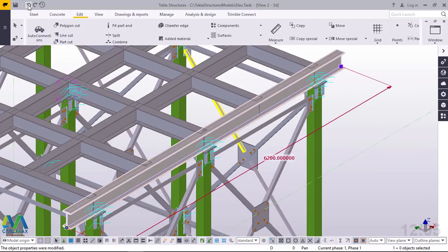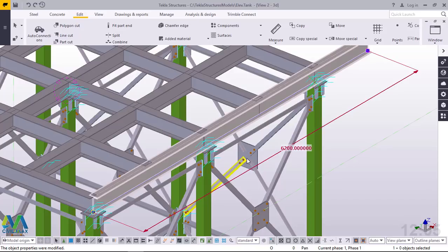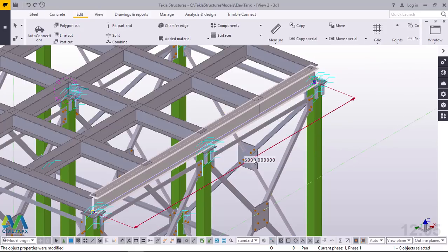Let me just type there 6.2 or 6200, and just go ahead and click enter, and we'll see both ends extending. Let me just undo and do that for you once again. Once you've selected that, just click on this, then feed 6.2 here, and I'll just press enter on my keyboard right here, and you'll see both ends extending. Now what I didn't do was activate both sides to extend. So I'll just undo and come to the dimension itself and click this both end to extend.